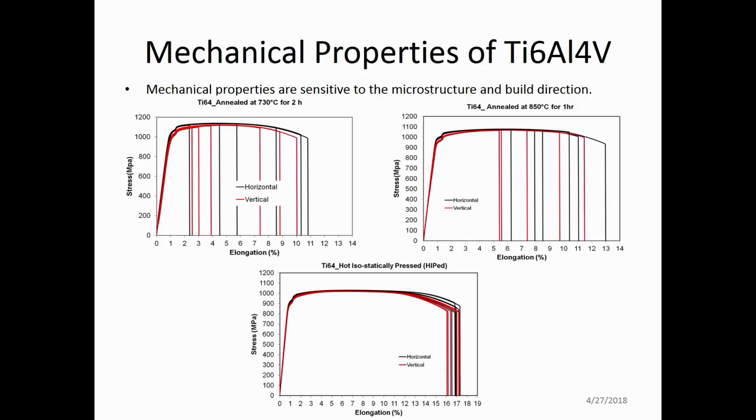So that's the difference in strength. Here, you don't see that much difference in the elongation, so it looks quite scattered. That may be more particular to Ti64 than anything else. But what you do notice is the elongation is relatively on the low side, so you should be getting 20 to 30%, and hopefully more like 30% elongation. But we're getting something which is relatively brittle, but relatively stronger. Our yield there is somewhere between 1,000 and 1,200. The yield on the quoted tables for a forged type Ti64 is probably about 200 MPa lower. So we've got high strength, low elongation.